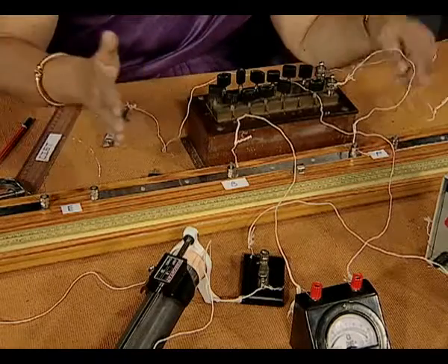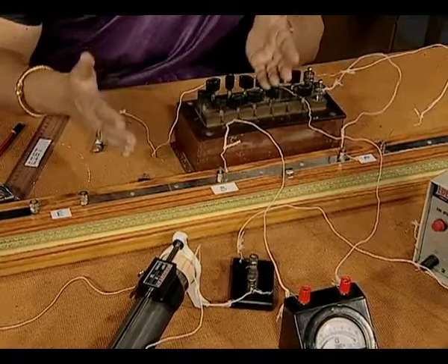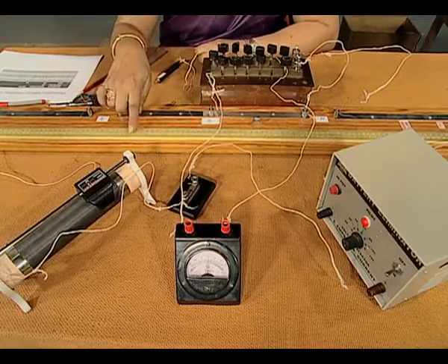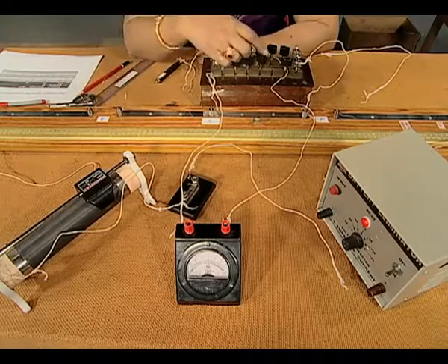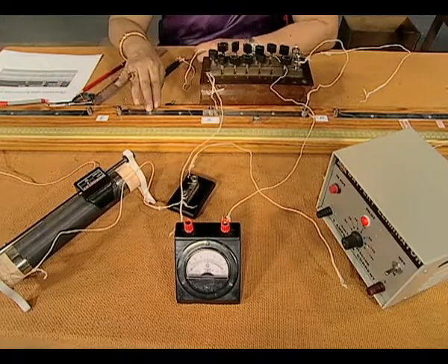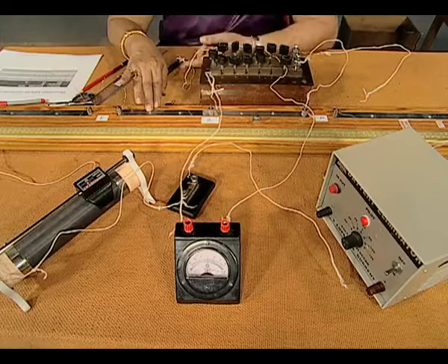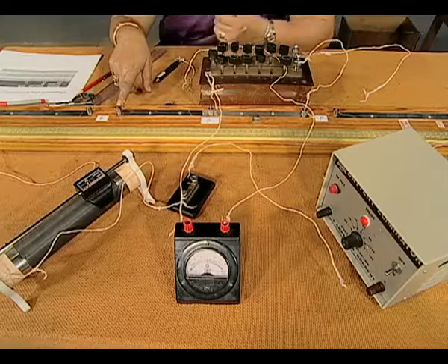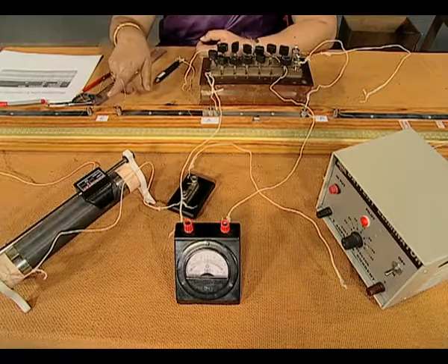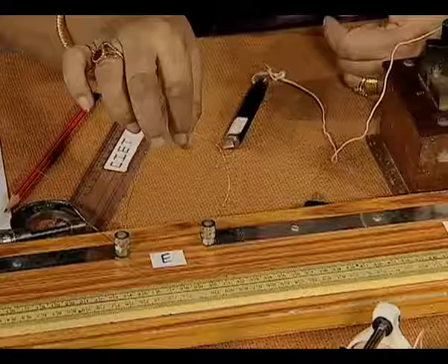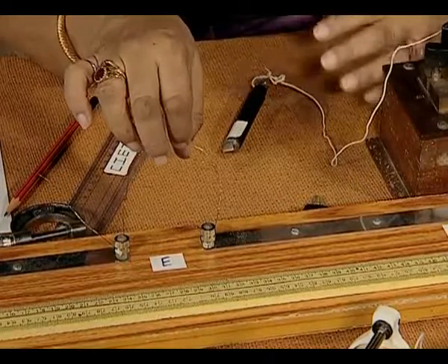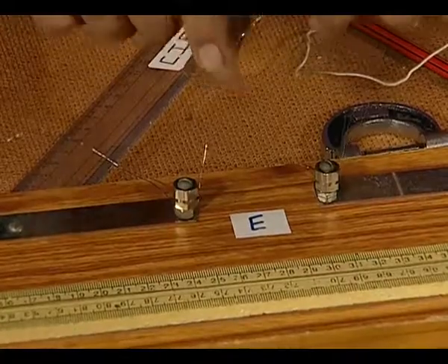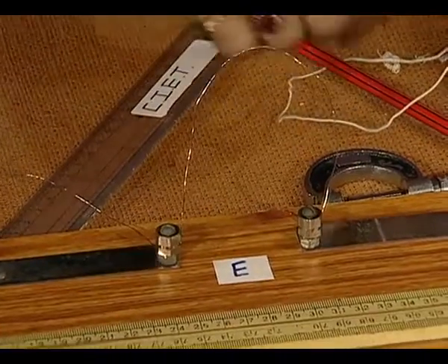All that will happen is that you will have a set of readings, and when you calculate the value for resistance again, you will have to make sure that you account for the ratio that you had selected in your Wheatstone bridge expression, so as to change it or convert it for the meter bridge expression, and therefore, the formula will just slightly change. Other than that, the value of the resistance is not going to, and you will get a set of 10 values for the resistance. Averaging it out, you will get an accurate value of the resistance of this wire.